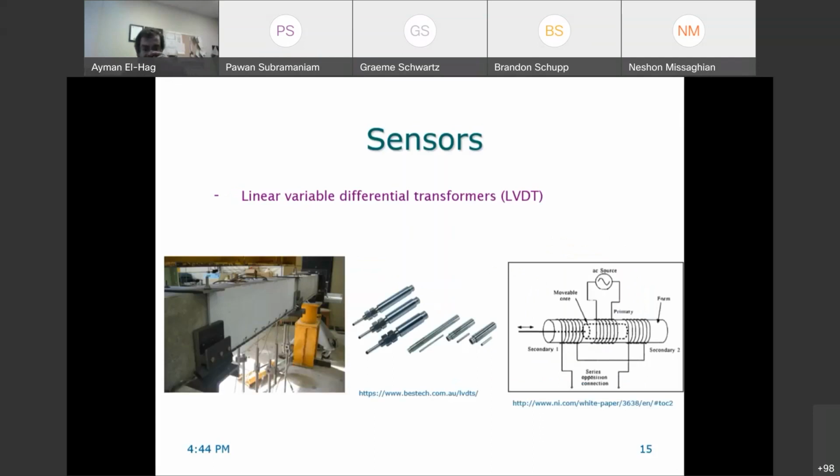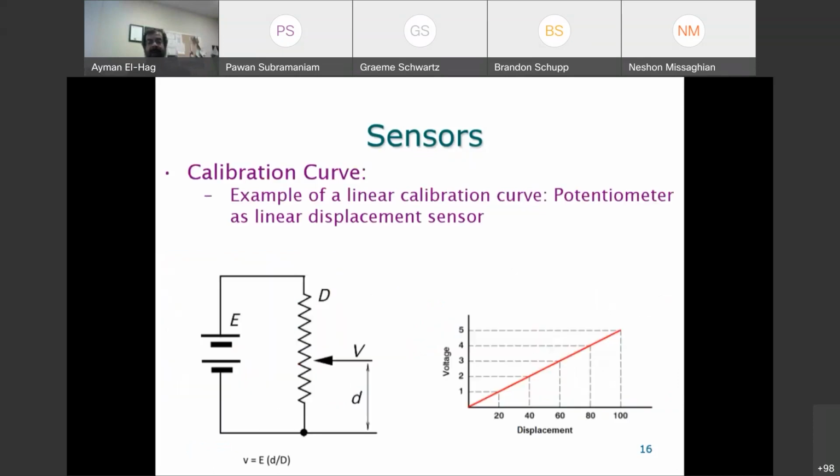As I said, the LVDT for short, or linear variable differential transformers, are used to measure deflection. So they are connecting, for example, in this beam, and once you apply forces here on this beam, those sensors or those LVDT will start to change their position, and this can be transferred into a change in the inductance. So this is called inductive sensors, which is also another type of the sensors that we will try to cover in this course.